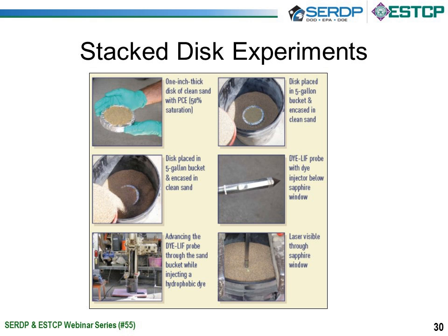Randy St. Germain then went out into his back yard and did various stacked disk experiments. So under very controlled conditions, he created disks about an inch thick with various combinations of clean sand and pure product, of PCE, TCE, other kinds of pure chlorinated solvents, buried them in buckets, and then in his backyard just drove the tool through the buckets dozens and dozens of times. There you can see the little laser coming out through the window there in the tool, and recorded those results.